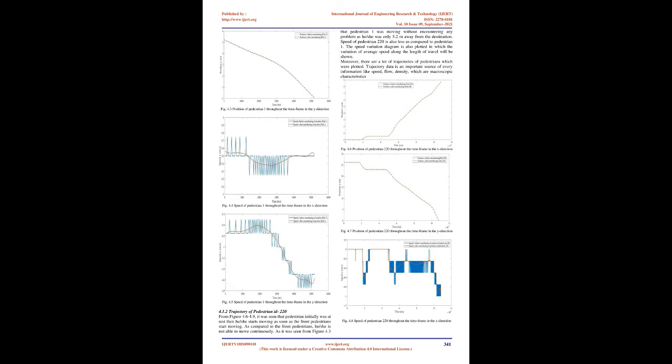Model calibration and validation. The model is applied to the real-world data, which is attained with the help of data collection, followed by data extraction and noise removal. The social force model is chosen to calibrate the real-world data as it can define various phenomena like lane formation, clogging and arching effects at exits.